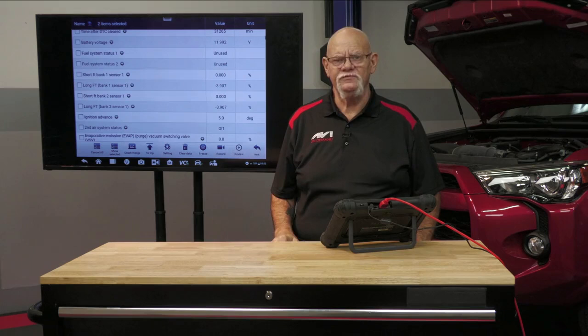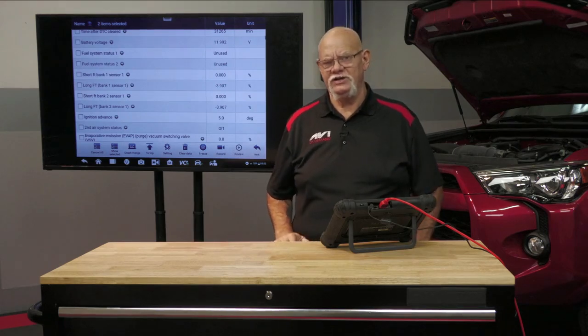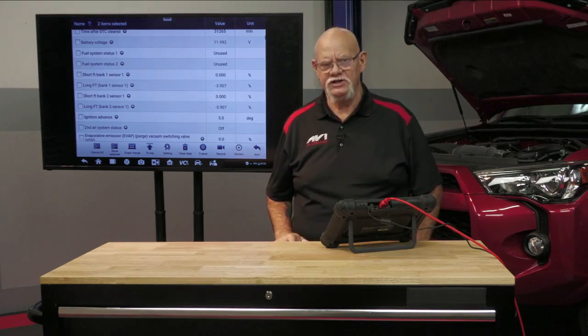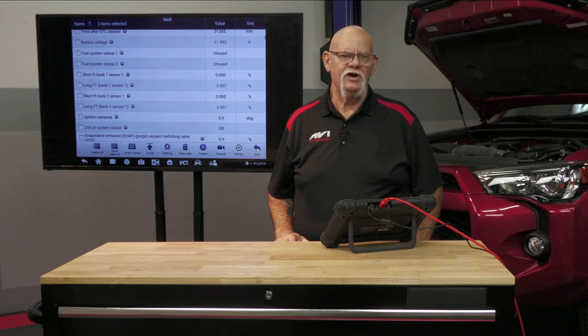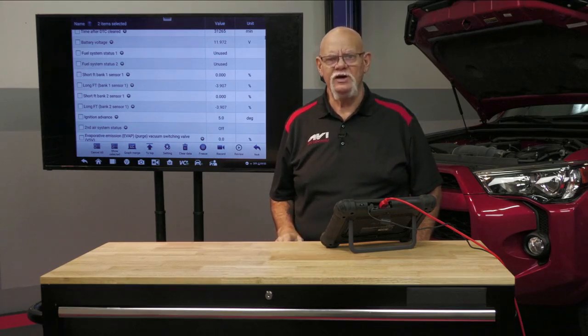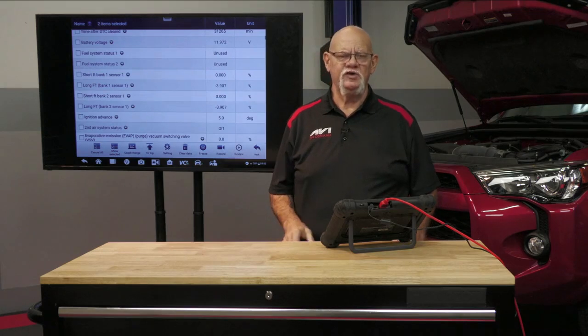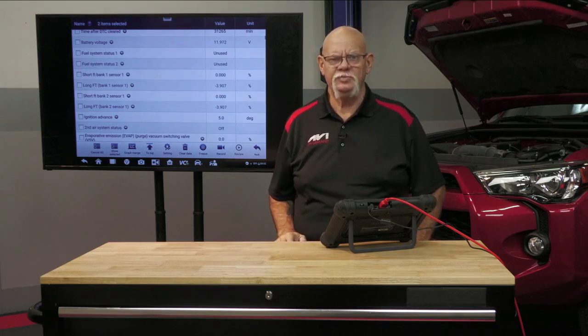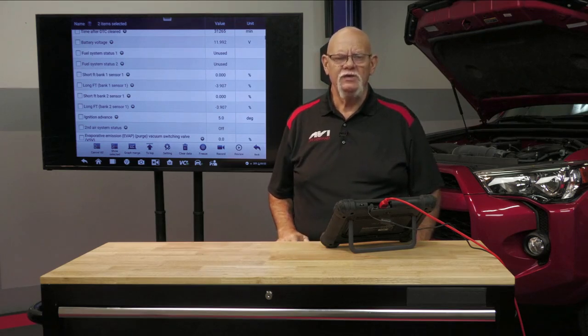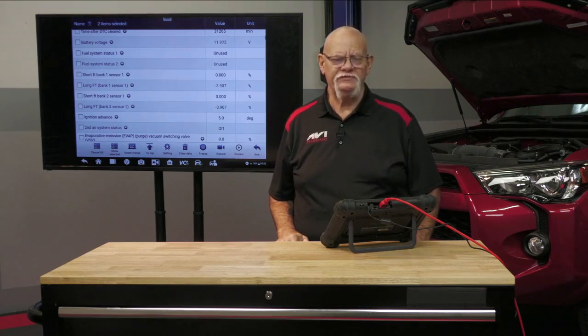Specifications on long-term fuel trim, I like to see them between -10 and +10. If they go above +10, we're probably going to set a P0172 or P0175 regarding which bank is rich. If they're below that, we're probably going to set a code P0171 or P0174 that we're leaner than where we want to be. But this is very valuable information, and you have to teach yourself, you have to condition